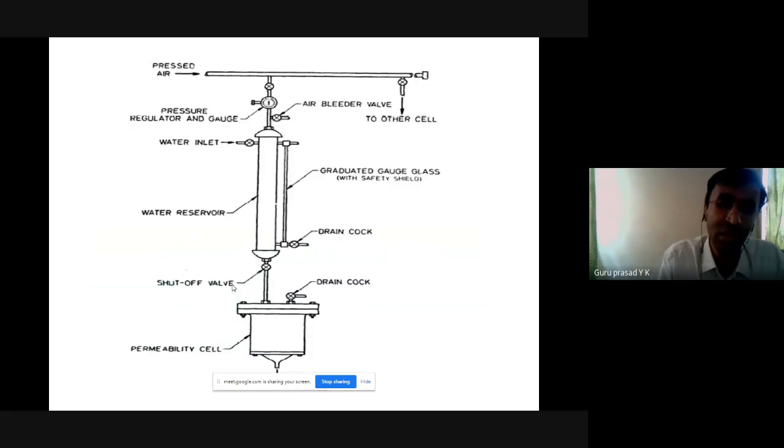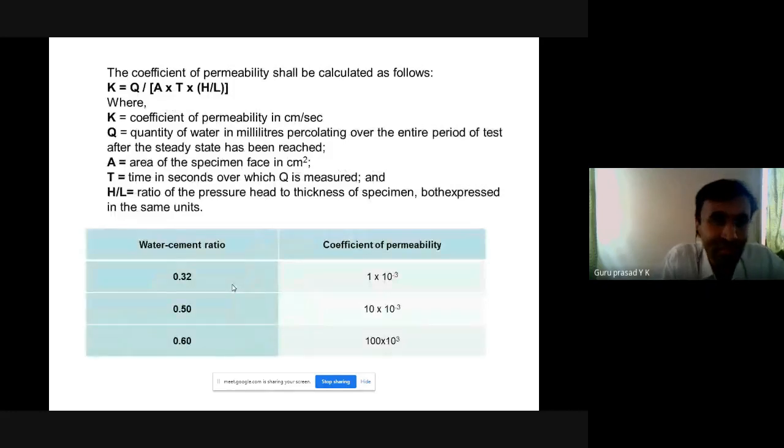This also applies to new concrete, mind you. If you cast slabs in a new building and they put water on for curing, allowing the water to be ponded on the slabs, and you see water dripping below, that also gives you an idea. If too much water is dripping, it tells you the concrete has a lot of voids. It has not been compacted well.